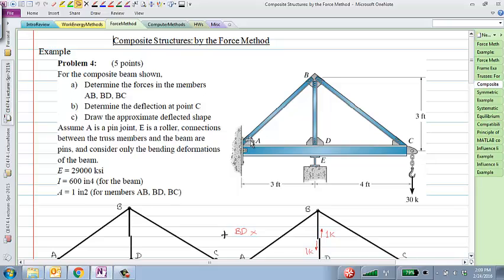And application of these types of structures, can you think why somebody might want to do this to this beam, which carries a load of something here? Why would you want to do something like that, Miles? Right, so if this truss was not here, then this beam would be forced to carry that entire load by itself, which would need a fairly bulky beam.